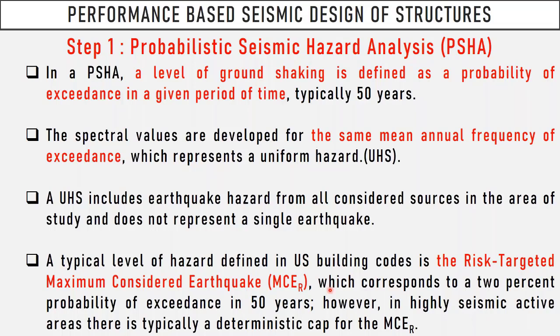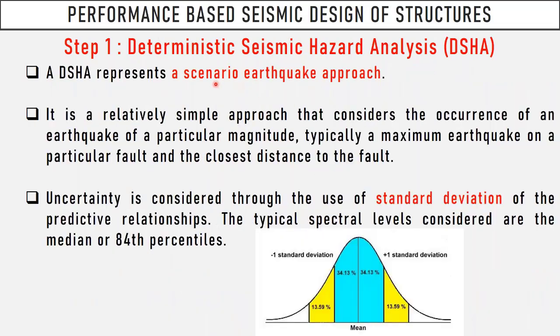It doesn't matter whether you are going to use probabilistic seismic hazard analysis or deterministic, which means a scenario approach. You may say that, okay, I'm going to design this building based on a specific event that is expected in its location. For instance, in my case, I'm living in Istanbul. We are expecting a major earthquake in Istanbul. One may say that I am going to design this building with a scenario earthquake that is expected in Istanbul. This is another approach.